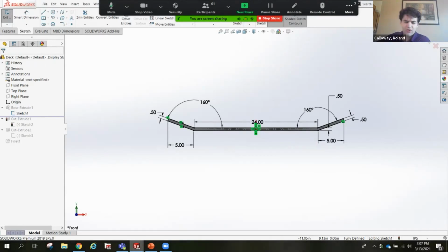What we're going to want to do is take a look at the physical thing you have in front of you and dimension everything out. So you figure out how thick the wood is, how long it is, and what the angle of these wings is. And then we're going to put that all into a simple 2D drawing.